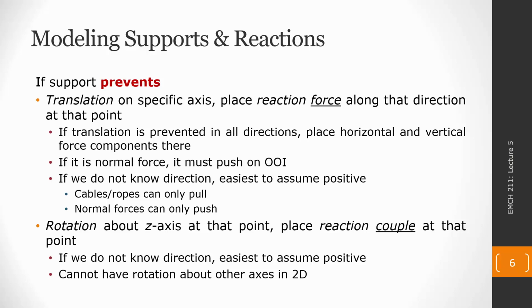So if we don't necessarily know upfront which direction is going to be countered, then we can just assume it's going to be positive and draw it as a counterclockwise moment. And once again, once we go through the math, we're going to see if the reaction moment that we put down is positive or negative, and that will tell us if our assumption was correct or not.